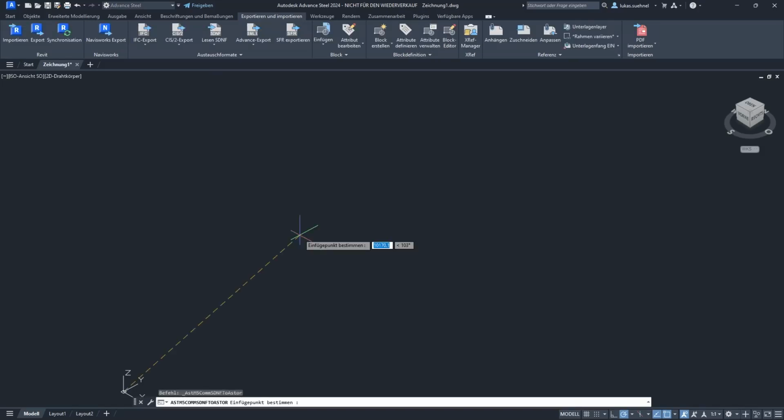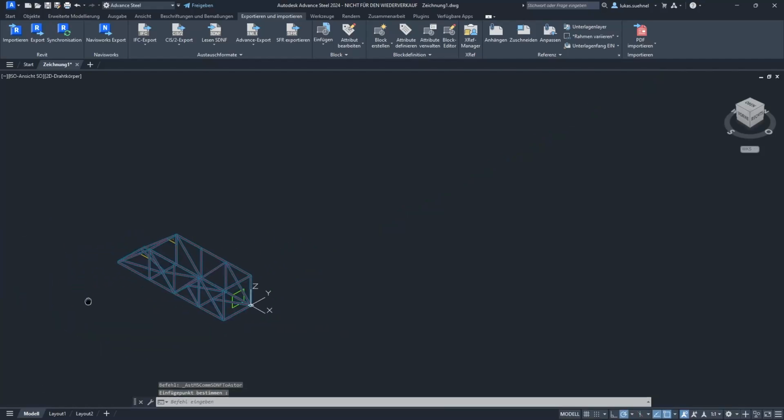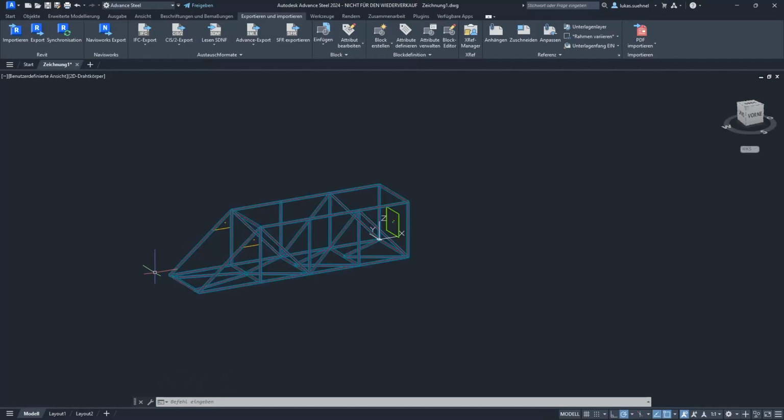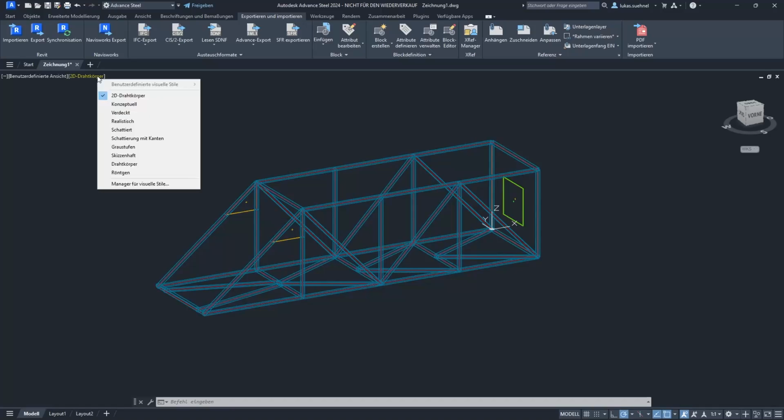Let's see. Sometimes we have to do a cross-section conversion similar to our program. Yeah, Advanced Steel is reading the cross-section names from the SDNF file, and if it doesn't know what Advanced Steel cross-section it should use, then you have to assign it manually. I did that for the German webinar already, so the window didn't pop up here, but we have the cross-sections, which is the most important part.